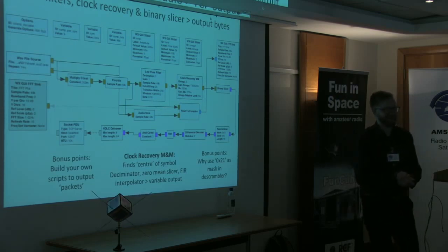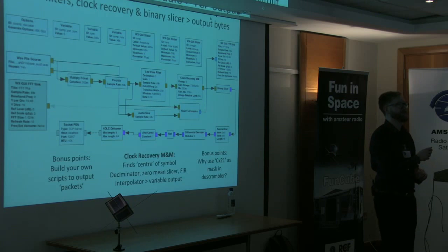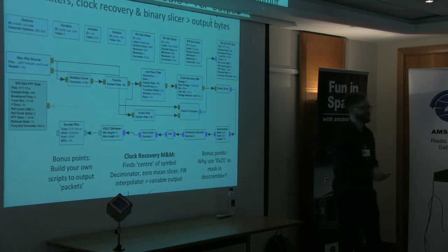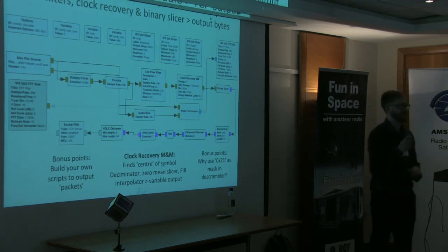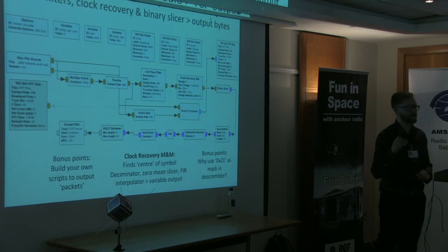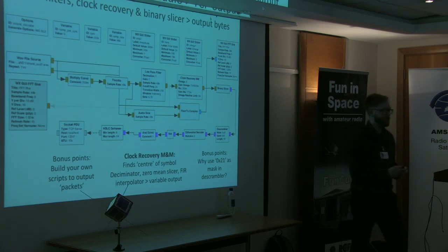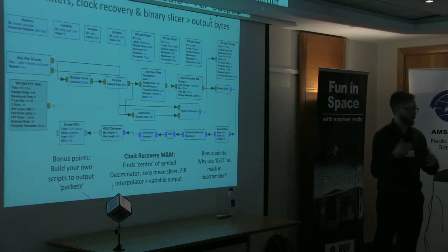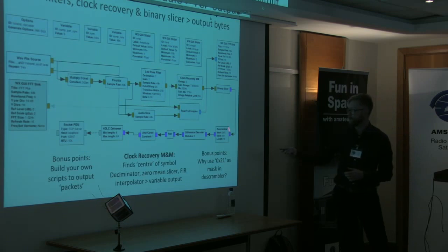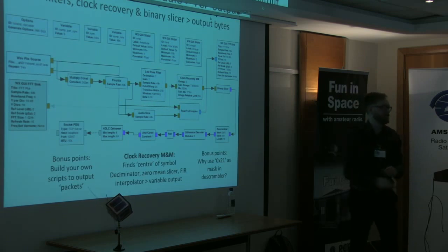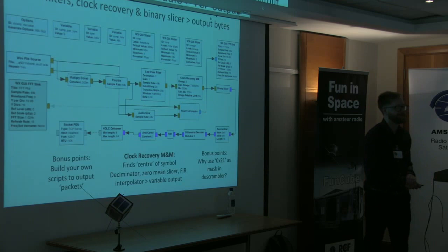Okay. It's actually based on the polynomials you're using for your scrambling. If you know what the polynomials are for a given scrambling type, a different demodulation type, whatever standard it is, whether it's CCSDS, HDLC, all these different things, these are polynomials that match 1 plus your 12th and your 17th bit.